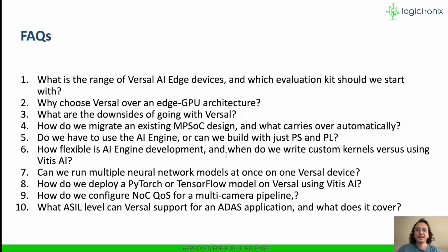How do we migrate an existing MPSoC design, and what carries over automatically? It is not a straightforward one-click migration. So the configurable logics, DSP blocks, and most of the on-chip memory can be used as it is, but the AXI interconnect, transceivers, and Ethernet MAC design might have to be rebuilt.